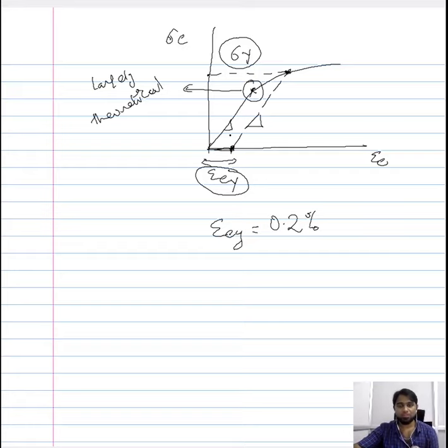And based on the intersection of this line on the stress strain curve, we arrive at a specific point that we refer to as the yield stress, and beyond the yield stress, whatever deformation the material exhibits, there is a plastic component or an irreversible component to it. The yield stress calculated by this approach is referred to as the offset yield stress.